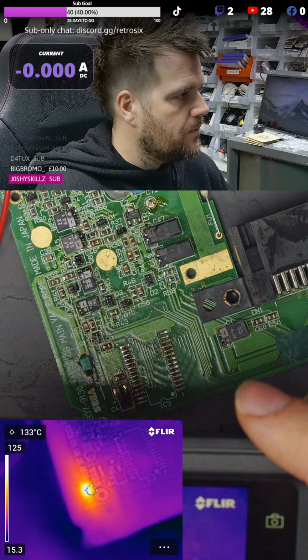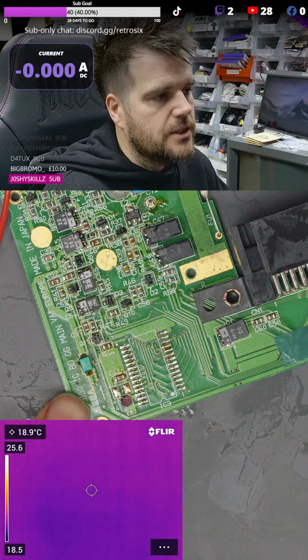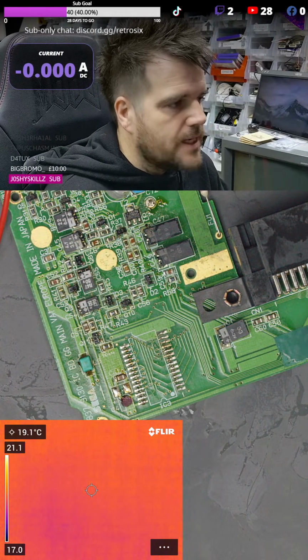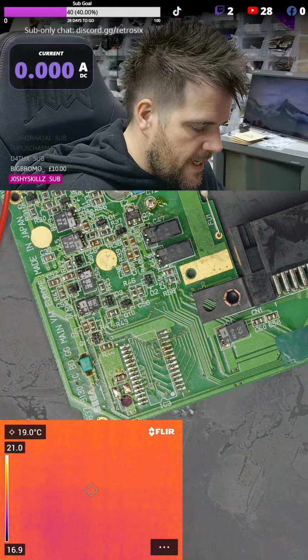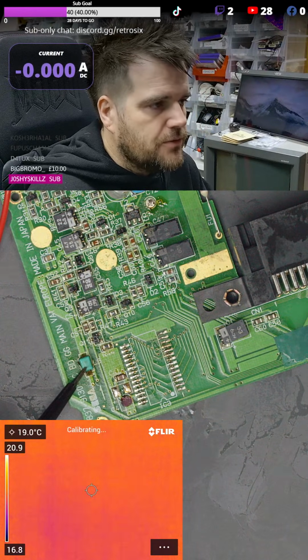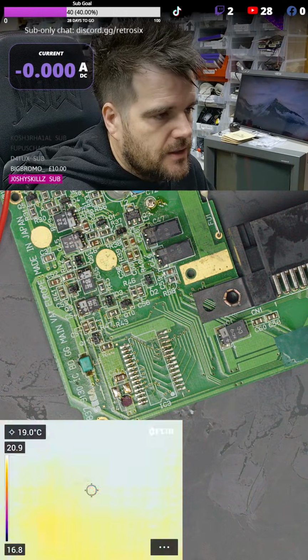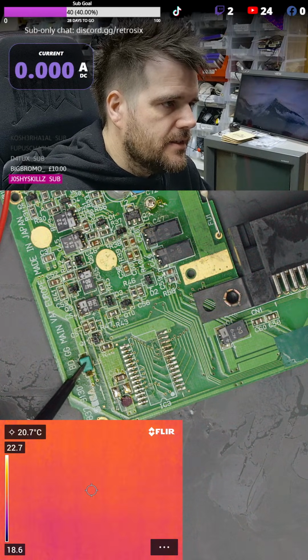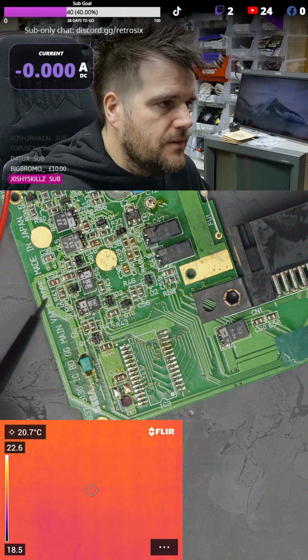So you might go, there's a short. Oh, it's this inductor. And you need to understand what things are as well. So the first red herring in finding shorts is that you might go, this component's faulty. So I'm now going to replace this component. Now, the only reason this is getting hot is this is on a Game Gear. This is the 5-volt rail.